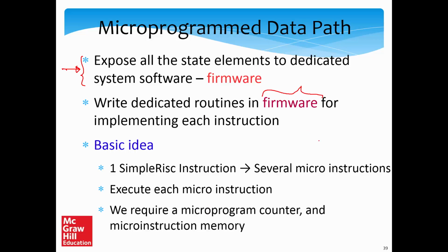The way we look at it, we have conventional software, we have conventional hardware, and we can have a small thin layer in the middle called firmware. Firmware is still software, but we still distinguish it because unlike traditional software, the firmware is loaded or stored in a specific location in hardware, and it is used to very intricately control all that the hardware does.